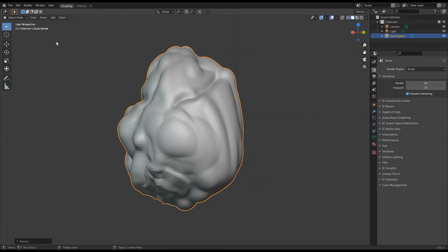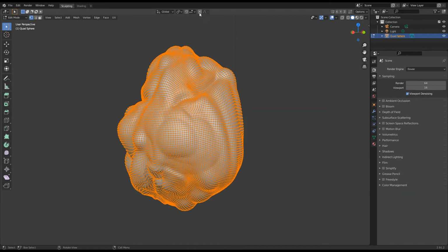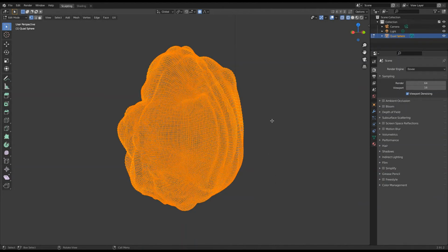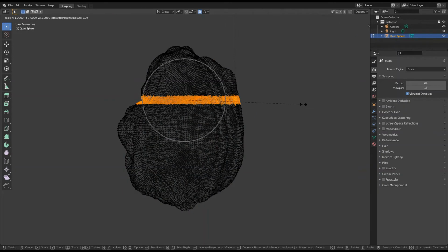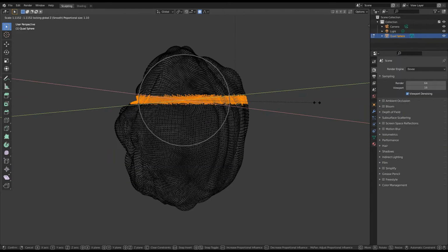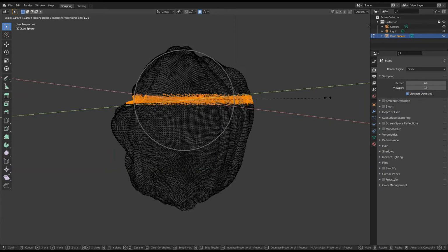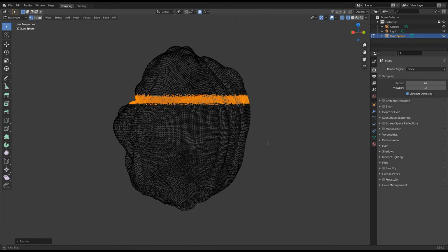And obviously, over in edit mode, you could put on your proportional editing and then wireframe, so that if we deselect now and put in a box select and scale not in the Z direction, you see we can be mixing editing and sculpting without a problem.